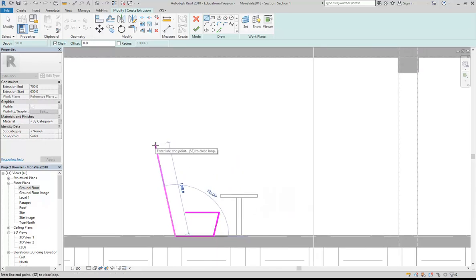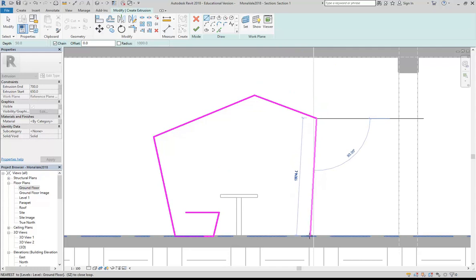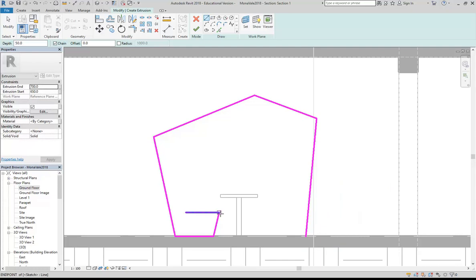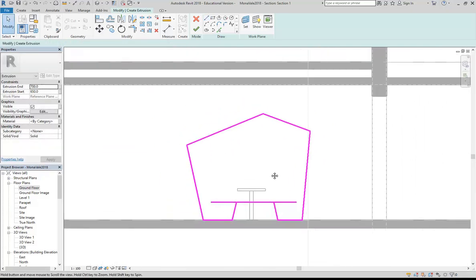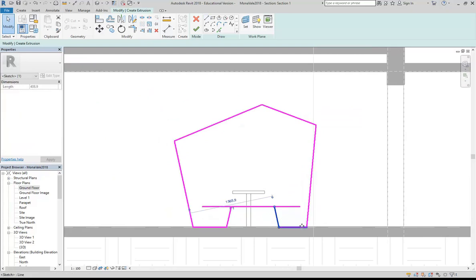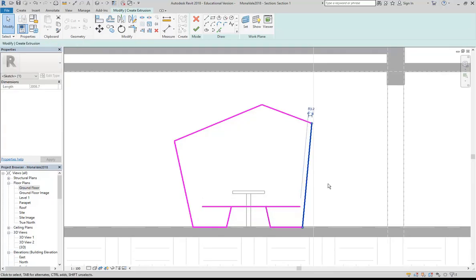So it's sort of an unusual shape that goes around and encloses this booth. So this is my time to be creative and do something, again, by eye that I'm happy with. Maybe something like that. So I'm just drawing another line from there to get the same height. And then doing the rest pretty much by eye. You can always select these lines using Control and use the arrow keys to nudge them into position. That's about right.